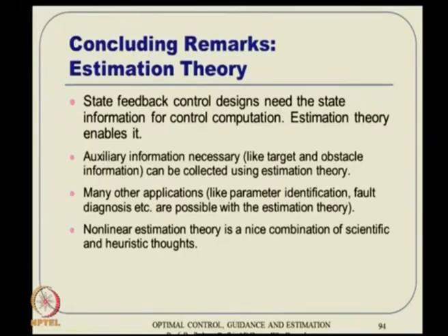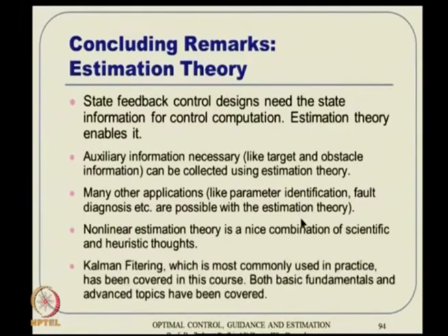And nonlinear estimation theory is a nice combination of scientific as well as heuristic thoughts. For example, like the extended Kalman filter, even though there is no theoretical guarantee, we know that it works very well, but it has difficulties in tuning also. The tuning part you can put into heuristic or experience, but once it starts working, it works in a very good way. Finally, Kalman filtering, which is most commonly used in practice, has been covered in this course in detail, both basic fundamentals as well as advanced topics like EKF, and even a little bit of UKF ideas we have also discussed.